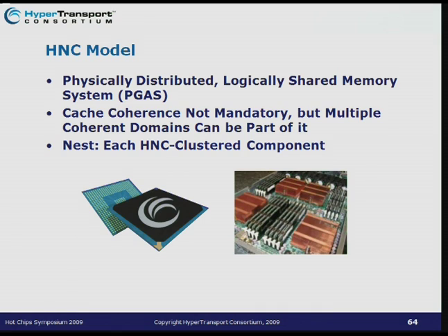When doing so, we not only defined the new packet format, but we wanted to make sure that we define the whole system model. We were considering physically distributed, logically shared memory systems, as opposed to current clusters, where shared memory basically reaches the scope of a single motherboard, and communication among different motherboards is implemented with message passing. We were envisioning systems where the whole system memory and the whole set of peripheral devices could be accessed from every core in the system, so that we provide support for a global address space, possibly partitioned. So in that vision, we wanted to extend HyperTransport technology to provide low-cost, efficient support for that system model.